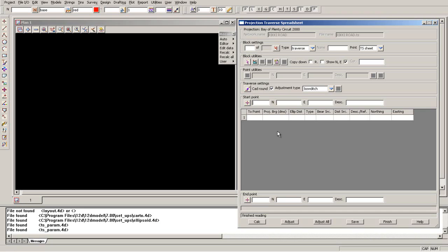So our start point we will call point 1 here, and I'll give it a northing 808,562.42, remembering our northings 800,000, and an easting of 405,986.23, and that will be our coordinate that I've made up for old iron tube 5.